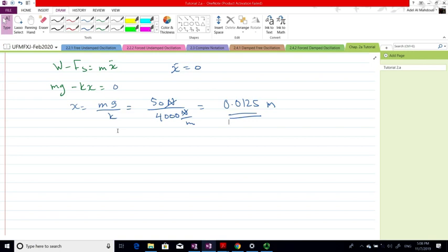It's going to be 0. While it's approaching 0, then the amplitude of oscillation, which is the maximum displacement, is going to be equal to F naught over K. Okay, F naught over K. So you have to remember static displacement. This is very important for you.